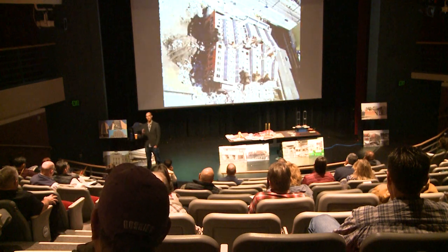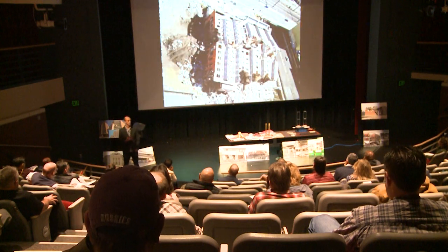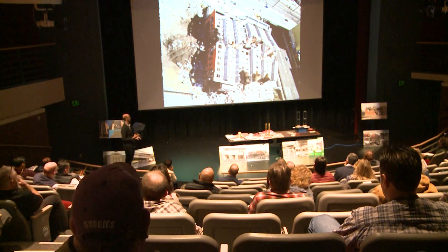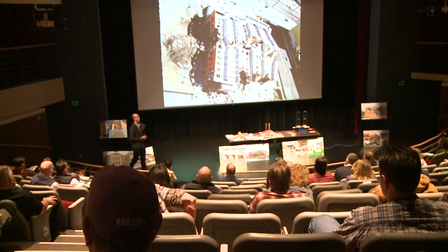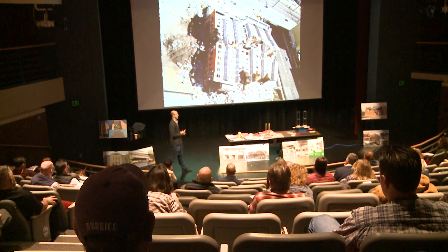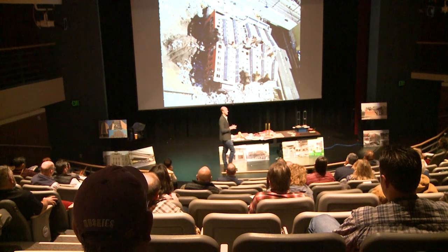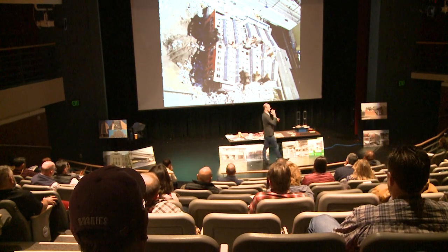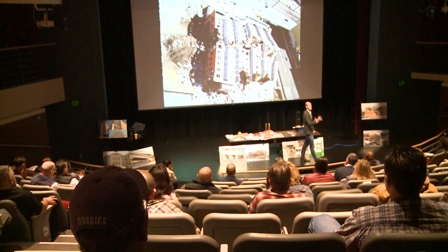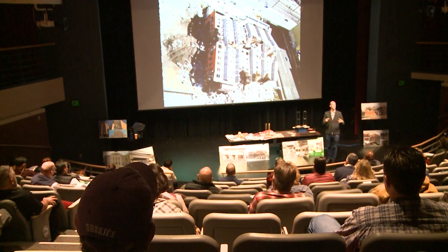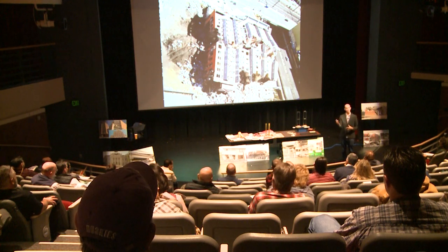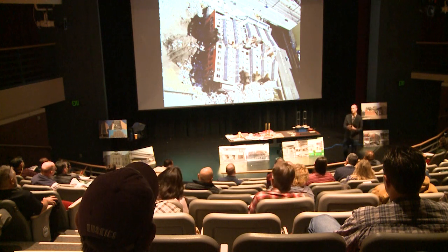I have another slide that shows the original construction because it was 1 year prior to the 2010 earthquake. And there was across the street a copy-paste building, also brand new, that had virtually no damage whatsoever. I think in part because it was oriented the other direction and there's some directional nature to this particular earthquake, and you can see just based on the footprint being sort of long and narrow, had very different dynamic characteristics in the weak axis compared to the strong axis of the overall global stiffness of the building.